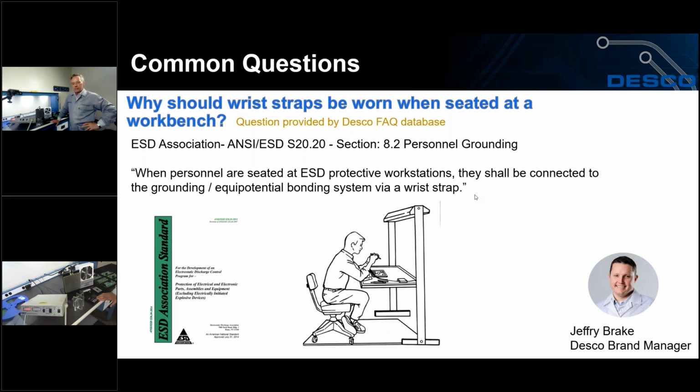Greg, do you have a chair that you can do a demonstration of that and show a charge generation? Yeah, so I'm going to slide my typical office chair over here, and I'm going to sit down in it. I've got my feet up on the chair ring right now. I'm going to touch the plate and you can see the amount of charge that I have on me. So now I'm going to put my foot grounder on my conductive floor and you'll see that the charge is off. Once I pick my foot back up, the charge comes right back again.